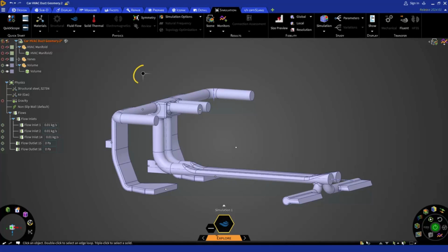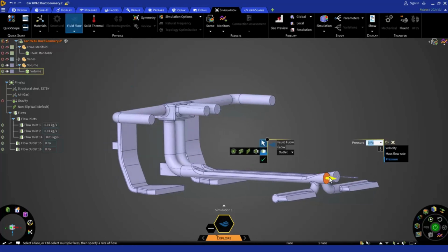There is one more alternative way to set up the physics. Click on the heads on your screen to open the heads-up display or HUD. Here in this HUD, you have many shortcut buttons like modeling, selection, and physics. You can use hex to quickly access these tools. Here I am going in physics and then fluids and selecting flow and then applying pressure outlet boundary condition.